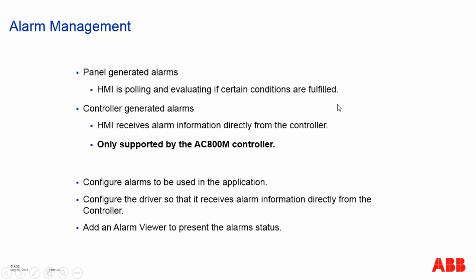But in the case of the AC800M controller and MMS driver, we can also use controller-generated alarms. It means that the alarms are handled in the PLC directly, and the HMI is just receiving the alarm information directly from the controller, which will make it much quicker to develop the application and easier to maintain.